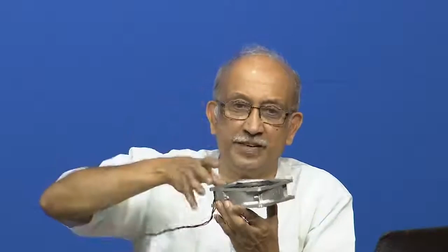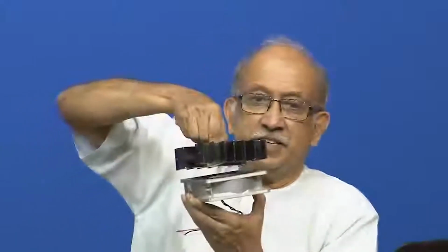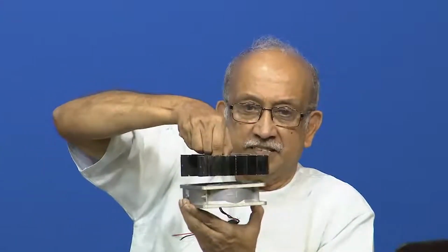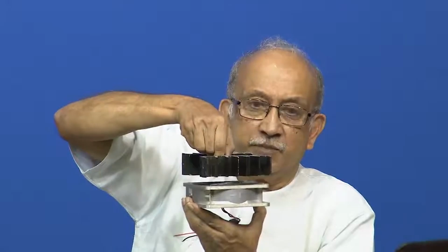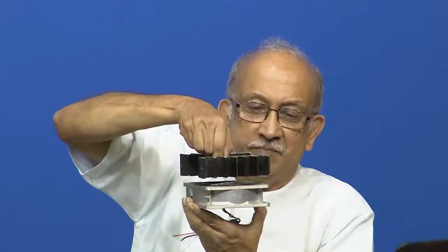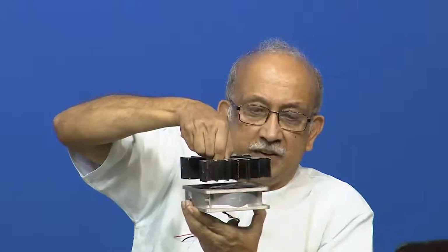Having done this, all I need to do now is, I have a fan. Now I need to take that little, is it blowing or anything? Earlier itself I have told you about it. It is much more convenient if you always have cold air sucked by the fan, and the fan sees the cold air only, and afterwards you have our heat sinks and things here. Only for purposes of illustration, I will show you here. Imagine we have one device here with a little bit of, for the flow to develop you require at least 10 millimeters, then only the flow develops freely.